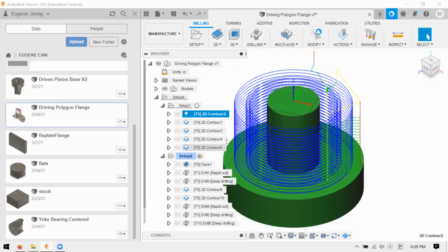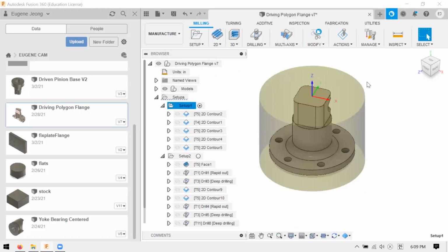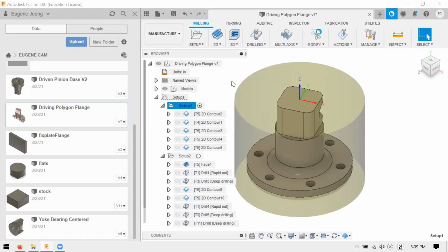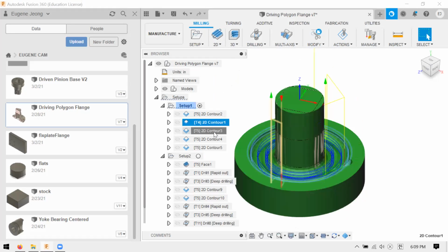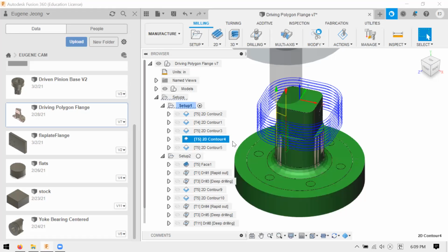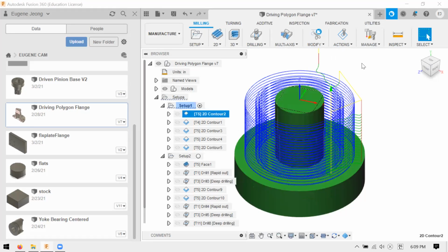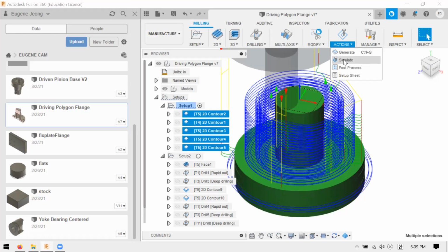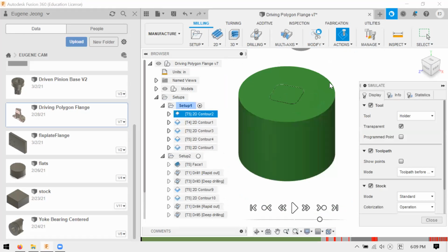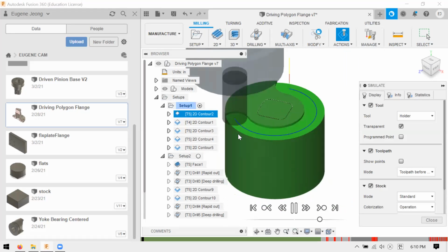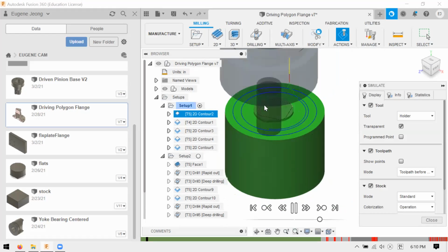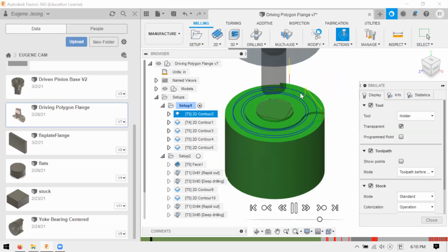And just like that, I can create a list of things that I want the machine to make. As I go through each of these contours, you can see these lines, which are the tool paths that the machine will be told to follow based on the G code that I generate. To give you an idea of how CNC milling works, one thing Fusion lets you do is create this simulation. Let's say that I started with some piece of steel in the shape of this green cylinder. Then the end mill, which is the cutting part of the milling machine, that's the little gray transparent cylinder, would come in and slowly remove material in the way that you're seeing.